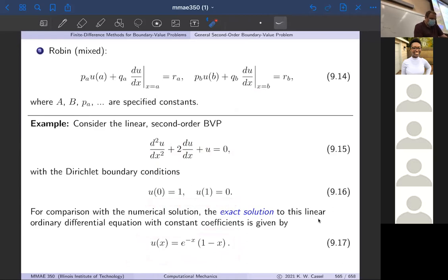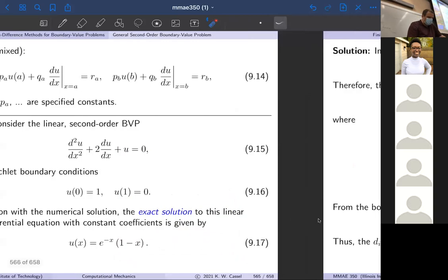These are given. At x is equal to 0, u is 1. At x equals 1, u is 0. Those are the boundary conditions. So we have the exact solution so we can compare it, but we're going to pretend like we don't know this and continue on and do this numerically. So presumably step 1's already been done to get the governing equation. Then we do step 2 to discretize exactly like we just did for the extended fin case.